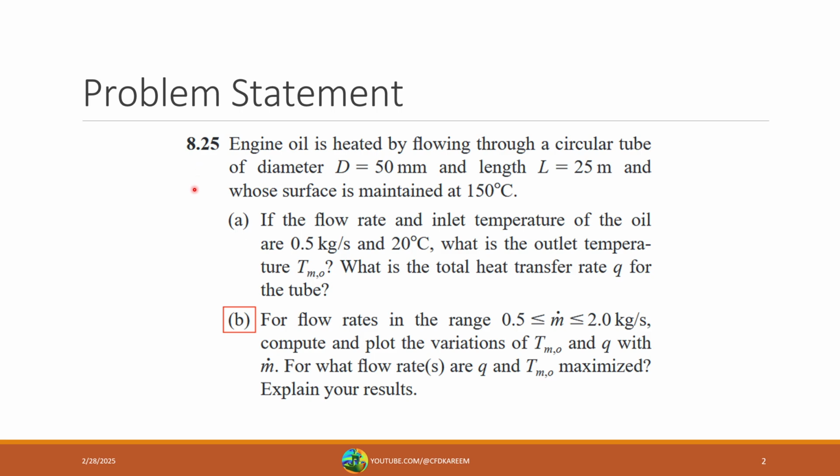150 degrees C. We're asked in the first part, if the flow rate and inlet temperature of the oil are 0.5 kilogram per second at 20 degrees C, what is the mean outlet temperature, T_m,o, and what is the total heat transfer rate Q for the tube?